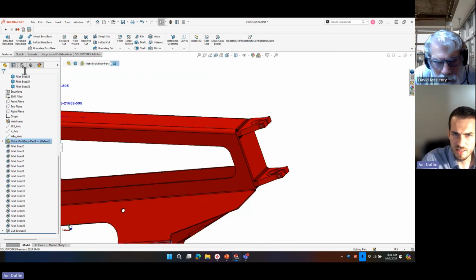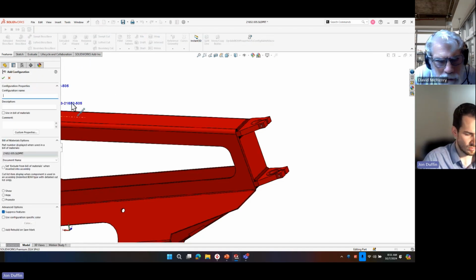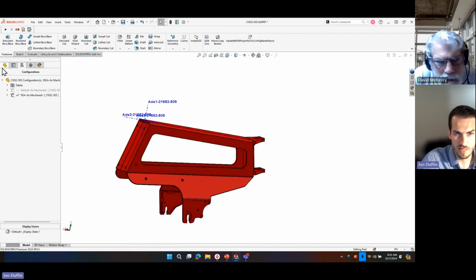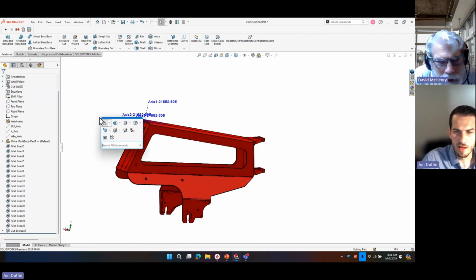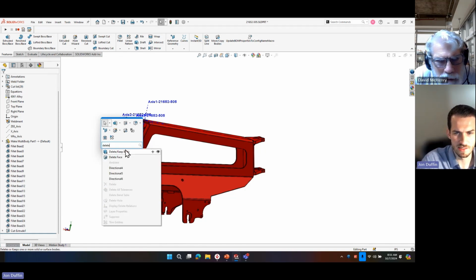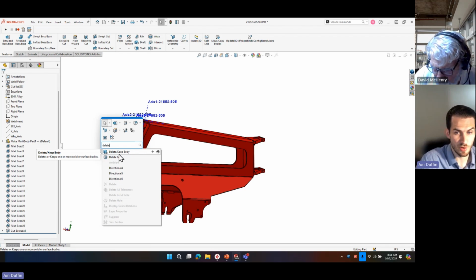Okay. So probably to simplify things, absolutely right, we'll add an FEA configuration on this. And then we can delete out maybe the bodies that don't matter. I mean, we could exclude them from the analysis if we're doing a full-blown one, but this Delete/Keep Body command allows me, in my feature tree, to delete the body. So it's still there if I suppress this feature. But at this point, it lets me delete out bodies that maybe we don't care about for this analysis.